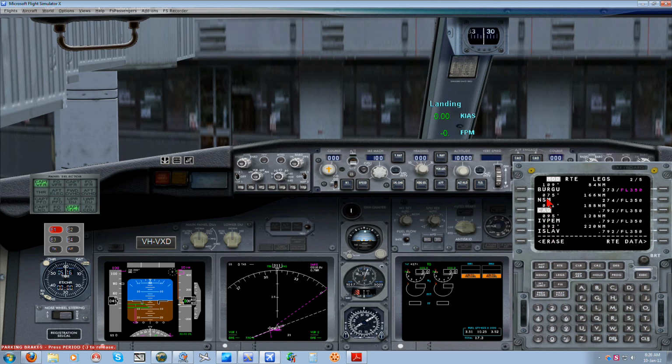So you just go through and make sure that there are no more route discontinuities, and so far so good, all the way through to Melbourne. Okay, so we just double check everything, make sure it's all looking good: no route discontinuities, no double ups of waypoints, no gaps. We're not flying back to Perth, which would make no sense at all, and everything's looking really good like it should. Once all that's done and you're happy with that, you then click execute. Okay, so that has now programmed all that information into the FMC. That's the end of that. We're now finished on the FMC.